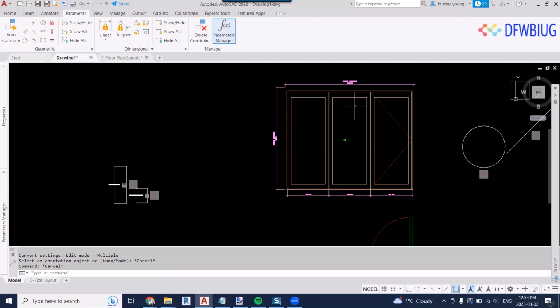And I can manipulate maybe just the length. And it would say, okay, this is 3 panels by 96 inches long. It's going to be this much for each panel, the frame's this size, and it will parametrically modify it for me. So I don't need to do anything. This makes it really good for companies and products that the product is the same but available in various sizes. Why do the work more than once? Don't do that. Got better things to do with your time.